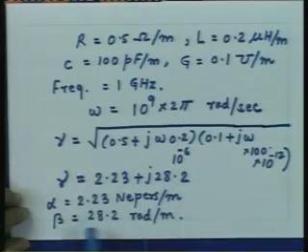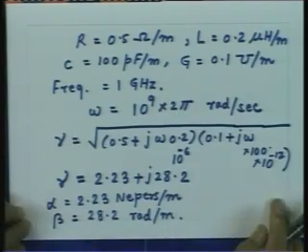Let us now apply this to the voltage expression on the transmission line. Let us say I have a travelling wave on a transmission line. The alpha and beta for the transmission line are given by this now, because the primary constants of the line were given by these parameters. Let us say that at some instant of time and at some location on the line, which we call x equal to 0, t equal to 0, the voltage measured was some value, and we want to find out what the voltage would be at some other point on the line at some other time.